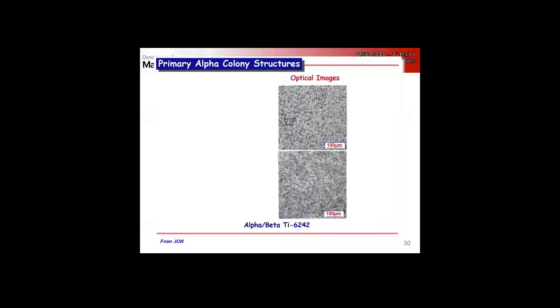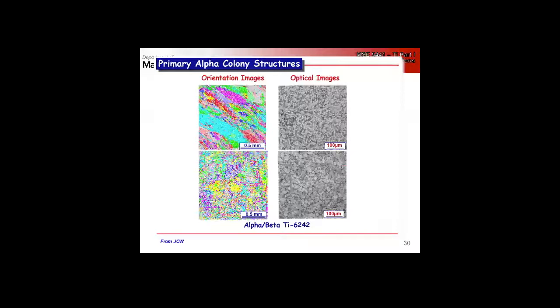And basically anything you run on this, X-ray diffraction to get macroscopic texture, chemistry, EDS or WDS to get composition fluctuations, you won't see anything. It wasn't until people were able to do EBSD that they saw things. So what is this big pink region here? Is it a single grain? What? No. What's the coloring on EBSD maps? Everyone in my mod sim right now should know this. Grain orientation. It's colored by grain orientation.